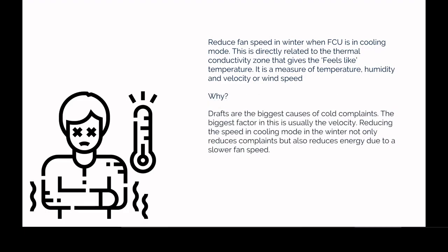Why is it important? Well, drafts are the biggest cause of cold complaints, and the biggest factor is usually the velocity. So a lot of speed blown from a grill or a duct. So reducing the speed in cooling mode in the winter.